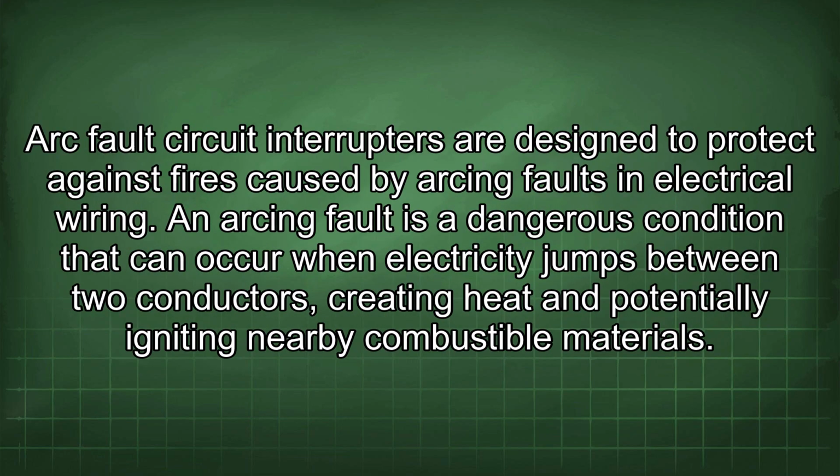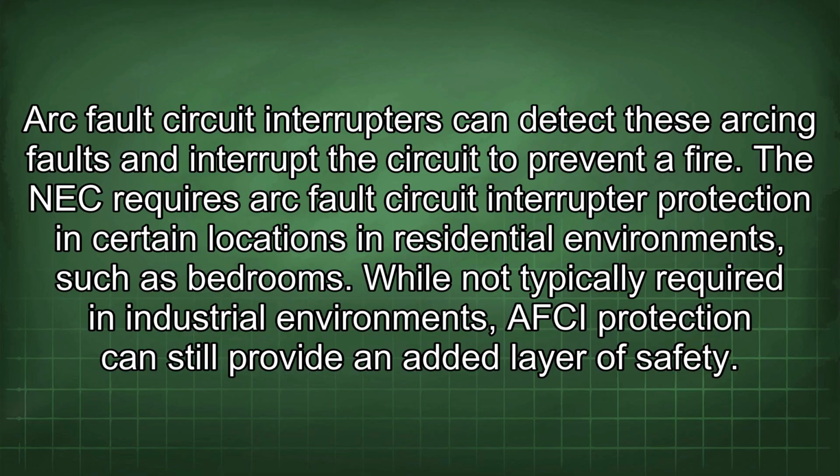Arc fault circuit interrupters are designed to protect against fires caused by arcing faults in electrical wiring. An arcing fault is a dangerous condition that can occur when electricity jumps between two conductors, creating heat and potentially igniting nearby combustible materials. Arc fault circuit interrupters can detect these arcing faults and interrupt the circuit to prevent a fire. The NEC requires arc fault circuit interrupter protection in certain locations in residential environments, such as bedrooms. While not typically required in industrial environments, AFCI protection can still provide an added layer of safety.